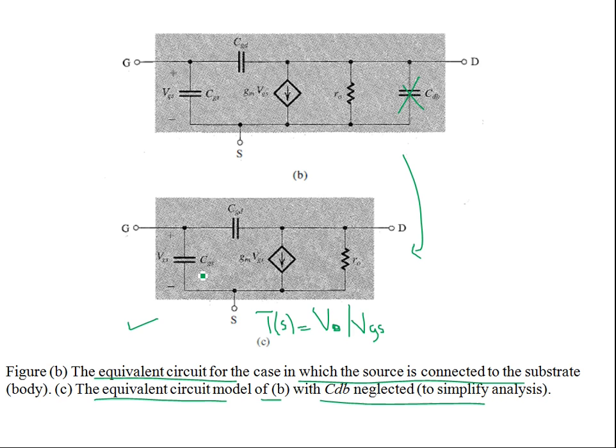If you recall in the previous circuits, we had not even considered CGD and CGS. We were leaving the internal gate capacitances of the MOSFET as open circuits. So between G and S there is no capacitance. R0 is due to the channel length modulation parameter, lambda, if it's there. So you have to include the output resistance between drain and source of the MOSFET, and that's internal to the MOSFET. It's not the external resistance.